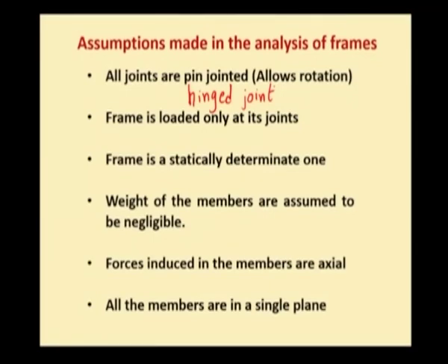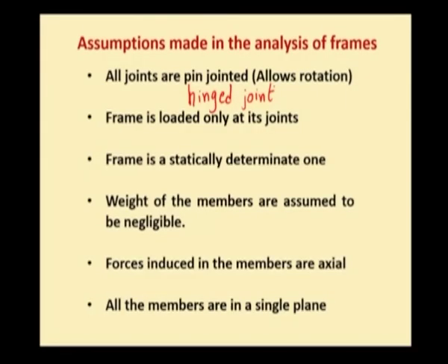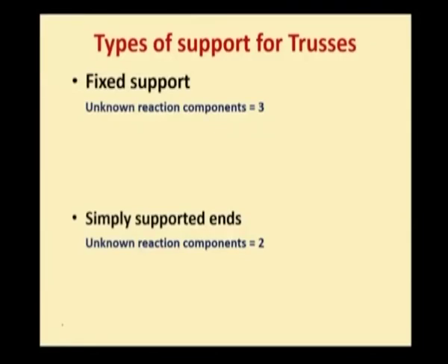Forces induced in the members are truly axial. Because of the external load, there will be some induced forces in the members. Those member forces are truly axial in nature. So, our aim is to determine the unknown member forces in the trusses because of the external load. All the members are in a single plane, which means that the truss is a 2-dimensional plane truss. Now, let us see the types of support for the trusses.